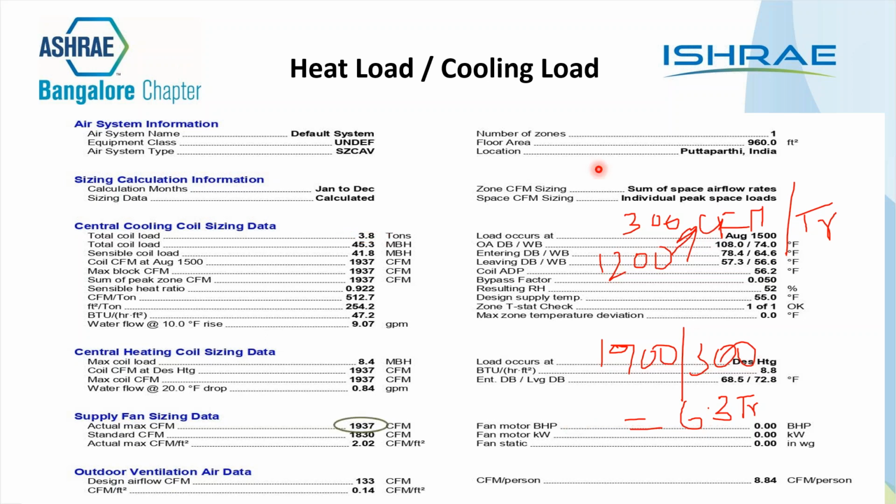Now, this is known as a diversity between indoor unit and outdoor unit. The difference between indoor unit and outdoor unit. Say, for example, what is the capacity of your outdoor unit? Your outdoor unit is 4 tons. Your indoor unit is 7 tons. This is just an example I am giving. It does not mean that you want a 7-ton system, you can use a 4-ton system. No, it is based on the heat load.